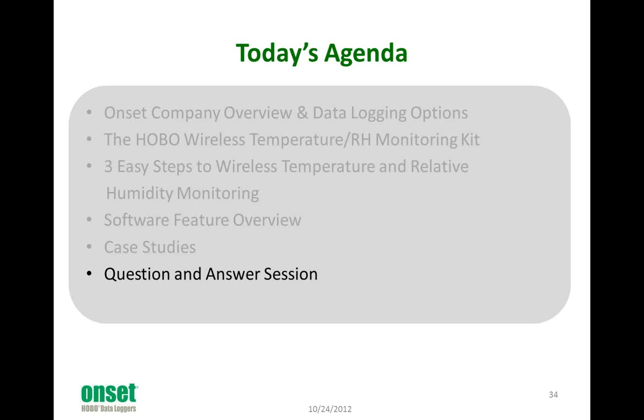In a museum with reinforced concrete structural walls, please elaborate on the use of repeaters to get the signal through. So there are a couple of ways we can go about this. Depending on how thick these walls are, you might be able to have a repeater on either side right up against the wall, so that the signal would be going through the wall, and you have one on the exact opposite side trying to catch that next signal.